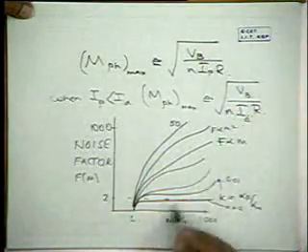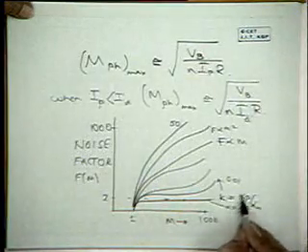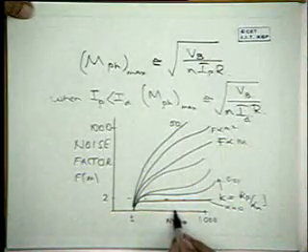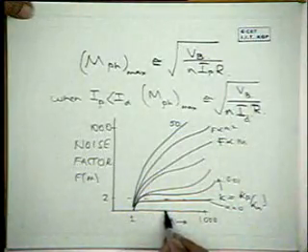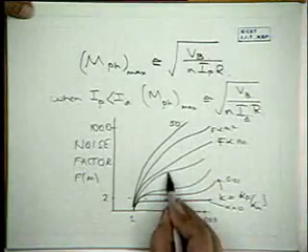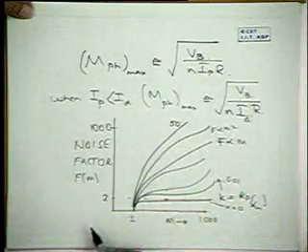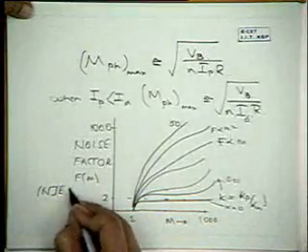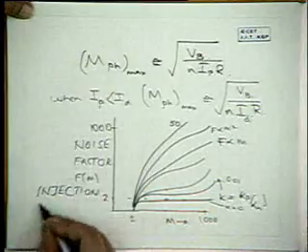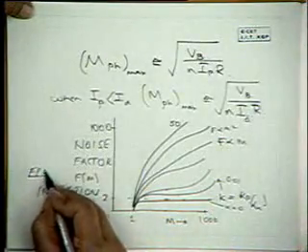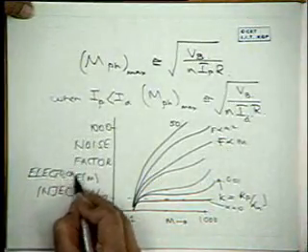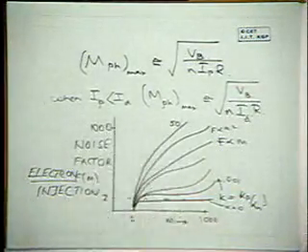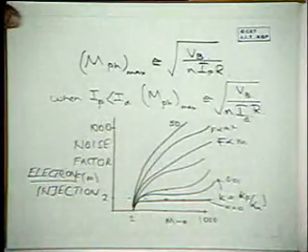So this just shows that given this value of alpha P and alpha by alpha N, which depends upon the material, okay, we can choose the value of M, which will give us the desirable noise, so that we won't have too much noise, and this obviously is valid only for electron injection. So the two graphs enable you to calculate the noise factor as well as the gain bandwidth for different devices.